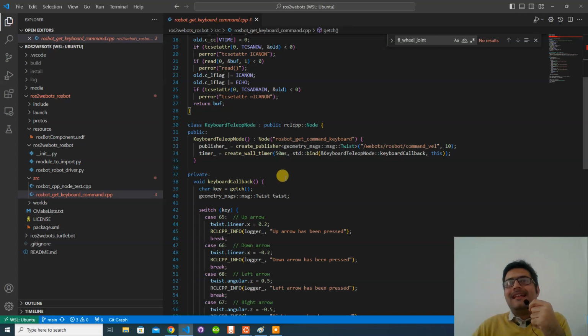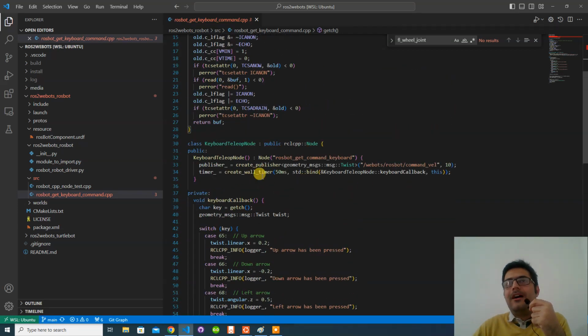Then, as you can see, I'm publishing a twist message on that topic, which the robot driver has subscribed to. The publishing is going to be done every 50 milliseconds.